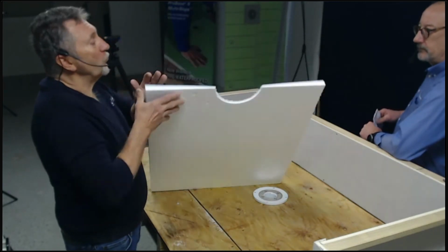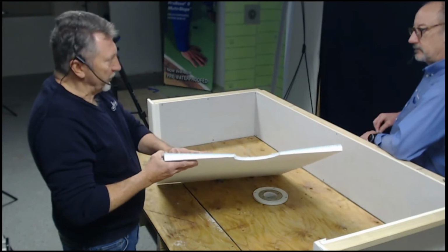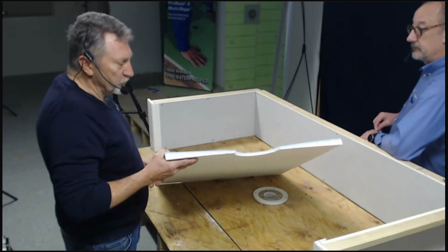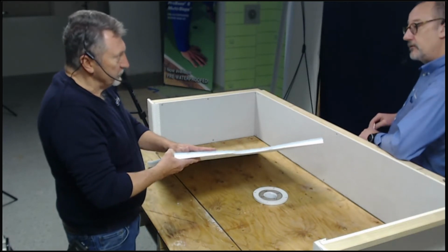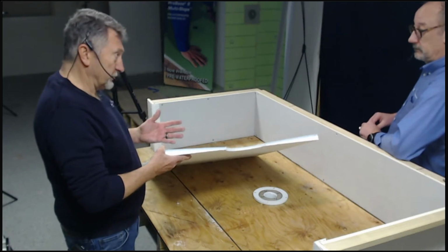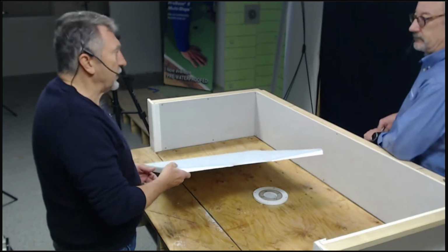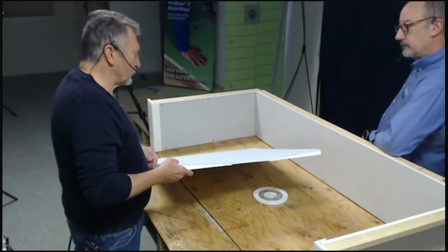We've actually applied a 1/4 inch of honeycomb structure to the top of our base. That adds a lot of strength. It adds a 235 PSI compression strength to the top of the base. What was the foam only, 3-pound? Foam only is around 35 to 80 PSI. Wow, so you've added a lot to it. A lot to it. So like I said, we don't care what size tile, penny rounds, pebbles, whatever. Don't have to worry about epoxy mortars.